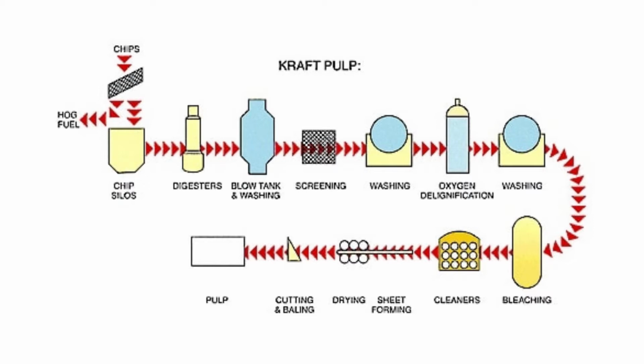In a living tree, the cellulose fibers are associated with a group of compounds known as lignin. Although important biologically, the presence of lignin lowers the quality of paper. The Kraft process removes lignin from cellulose by heating chipped wood in a solution of sodium hydroxide and sodium sulfide. This uses a lot of energy and also produces large volumes of pollutants. Even with restricted emissions, pulp and paper manufacturers that use the Kraft process often can be identified by a strong, offensive smell. The Kraft process generates hydrogen sulfide gas and other sulfur gas compounds as a byproduct.